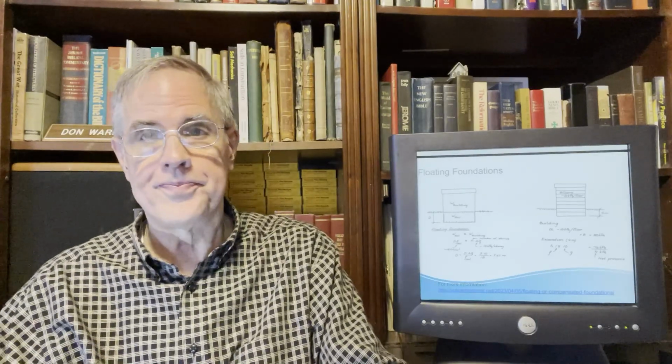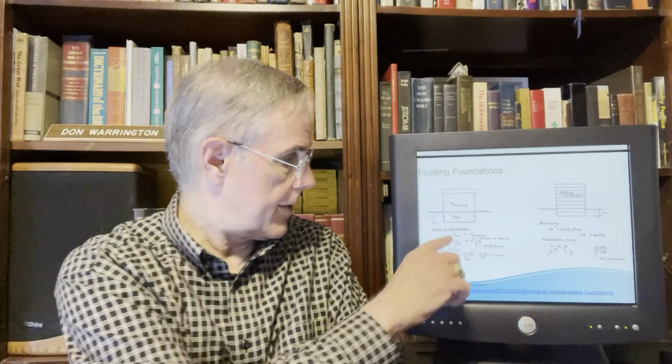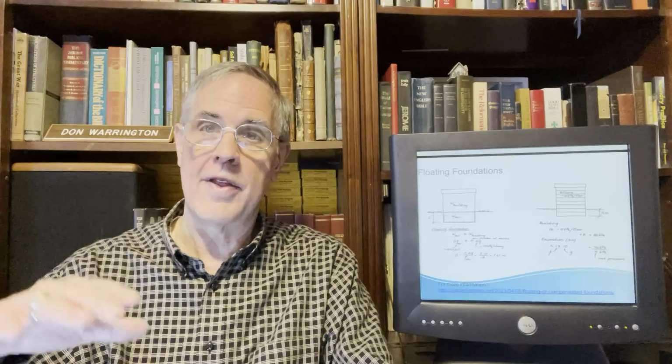So with that in mind, times rho, which is actually, he's got rho as 18 kilonewtons per cubic meter, and we all know, don't we, that that's a unit weight, that's not a density, is equal to the number of floors times the load per floor. In this particular case, he's got 10 kPa per floor, and you multiply by the number of floors. If you've got the same on each floor, then you get, voila, the building.